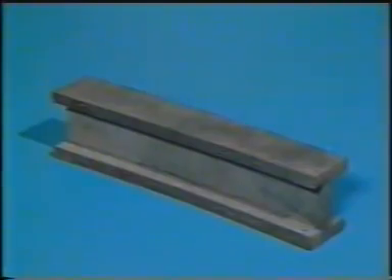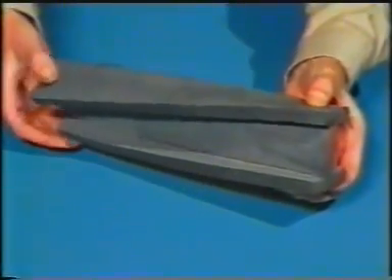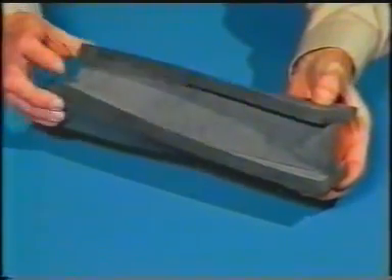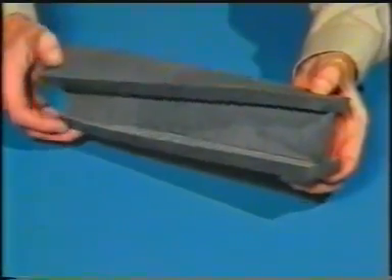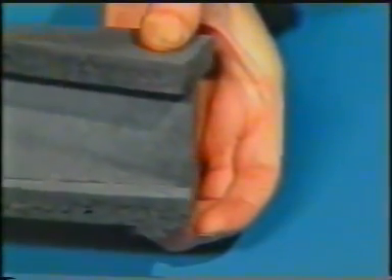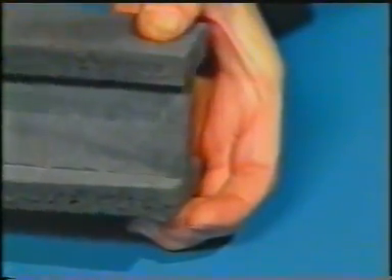There are other actions which are involved in the instability of beams. One of these is warping. For steel beams, actual warping deformations are very small and are barely visible, but they may be seen using the soft rubber model. This short beam is being subject to equal and opposite end couples, and torsion occurs. However, in addition to the primary twisting action, it can be seen that the end cross-sections no longer remain plane, but the elements of the cross-section distort out of the plane perpendicular to the longitudinal axis of the beam.